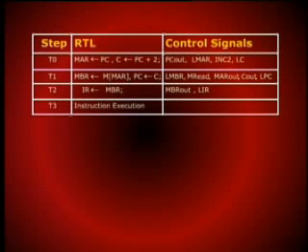LMAR is the control signal for the address register. Now, PC has to provide the data to the bus, and it cannot do that unless its tri-state buffer is activated. So to enable the program counter to provide its data to the bus, we need the out control signal, which is named PC out.